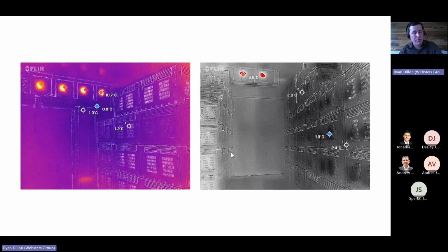So the fan provides more mechanical airflow, so you don't have to run the fan as often, because anything consuming an electrical load in a cold room, whether it's a light or a fan, pretty much all of it turns to heat anyway, which then needs to be rejected by the refrigeration compressor in the refrigeration cycle, which costs money and electricity. So designing for efficiency also relates to airflow and how you stack the cold room.